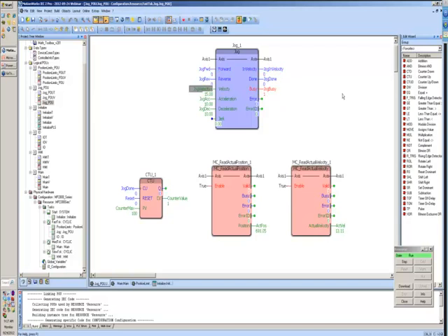And once we exit the block, for one cycle, the done bit will come on. Now we can't actually see that in our operation, so I put a count up timer here so that every time I execute a jog command, we can see that increments by 1. So that is coming on for one scan. We also have the error codes as well. These are the same error codes that the MC jog velocity uses.